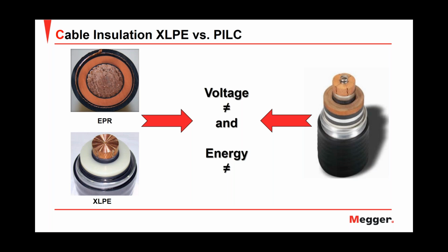But if, on the other hand, I have a paper insulated cable and I also have a pinhole fault, the fault will be filled with oil, and oil is a dielectric, which means that I will need more voltage to break down the pinhole fault in a paper insulated cable.